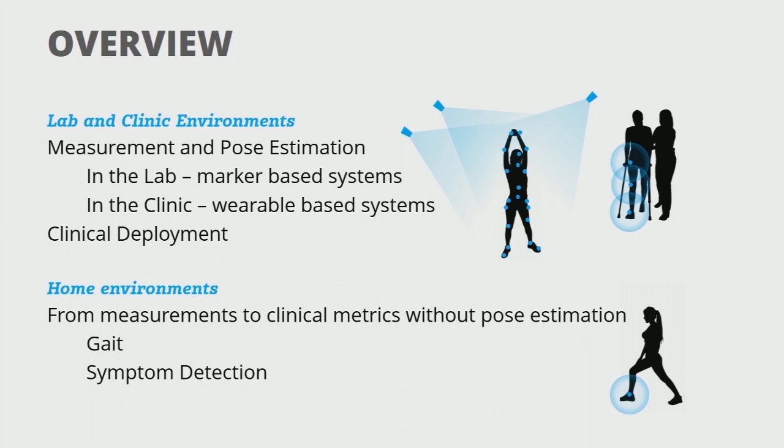First we collect the data, and typically the kind of data we collect is coming from motion capture. The demonstrator is wearing a number of markers, which are observed by cameras that are placed around the demonstrator, and these cameras triangulate the positions of the markers to generate a very accurate measurement of the 3D positions of the markers. And then that data is typically post-processed, and from there we generate the pose estimate or the joint angles. So I'll tell you a little bit about how to move from an offline treatment of this data into online treatment that can enable interactive applications.